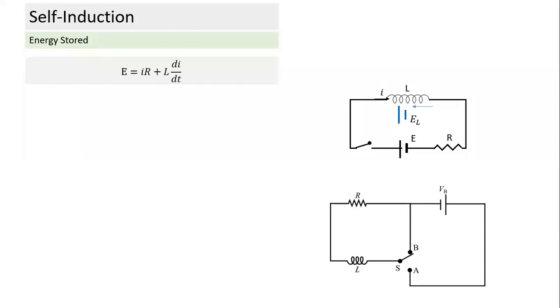Basically, what we do here is the circuit, and why we have drawn something like this. As long as the current is changing in the circuit, the inductor behaves like a battery. So we can replace it: an inductor has some resistance, and the resistance the inductor has has already been shown here separately. This R indicates the equivalent resistance of the whole loop. This R could include the resistance of the battery, the internal resistance of the inductor, and external resistance put together.